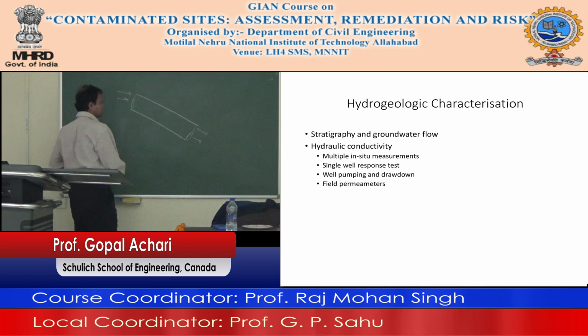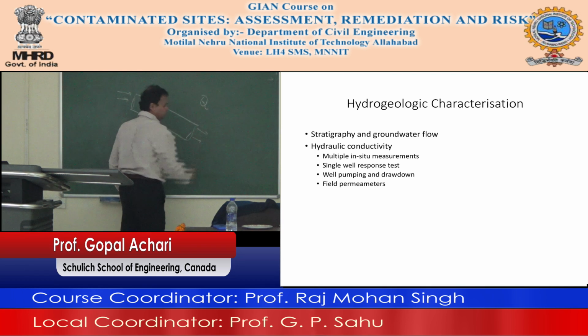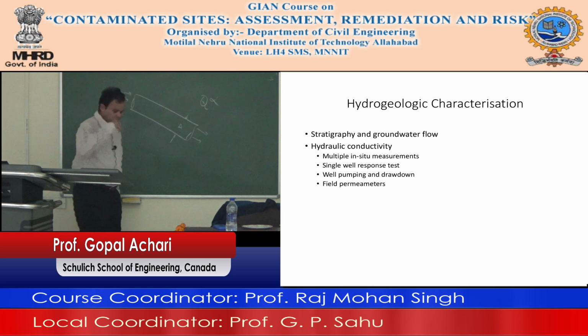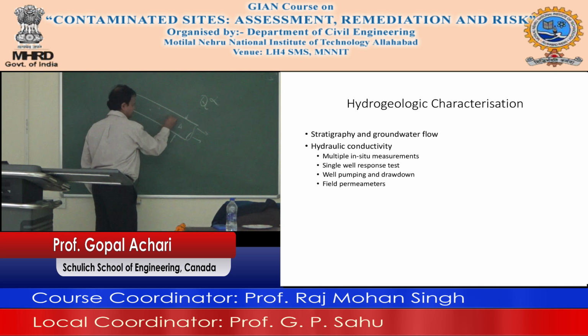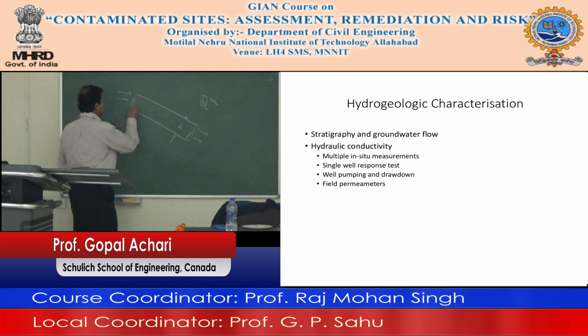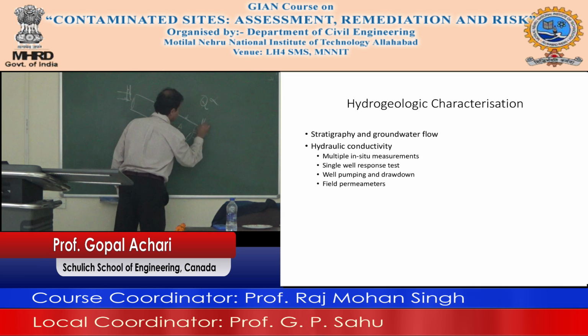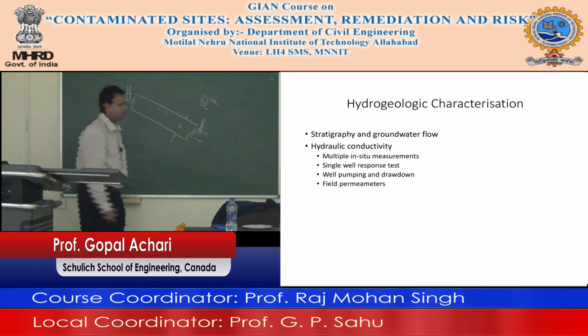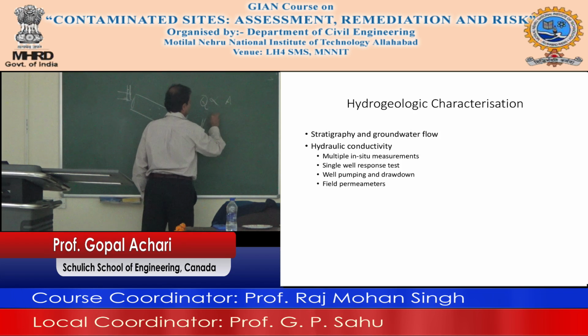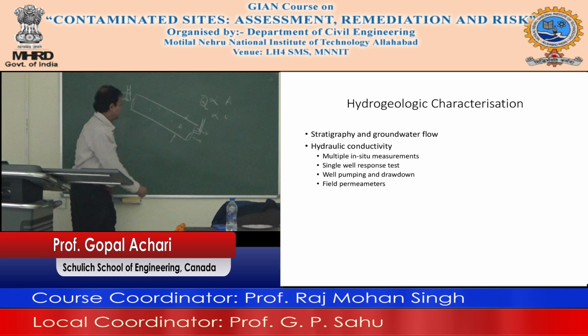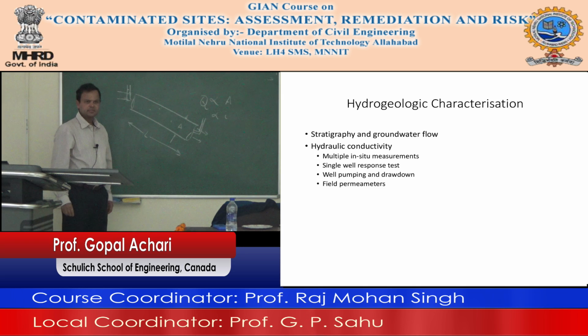Darcy conducted an experiment and found that the flow that goes through is proportional to the area, and this is filled with sand, by the way, and it is proportional to the hydraulic gradient, which, if I put a standpipe at these two ends, is the difference between the standpipe heights divided by the length. Are you with me on that? All of you? Okay.